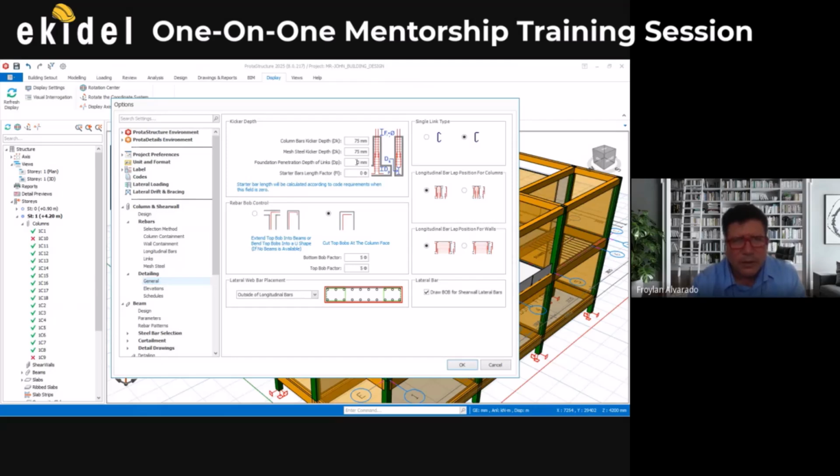penetration depth. Okay. The thing is that if you don't control that depth when you design, sometimes the programs want to give you huge footings, so you can control with what they start, you know. So I usually place the footing to 250, so that it starts at 250 and I can control what the program shoots out, no? And then same thing.